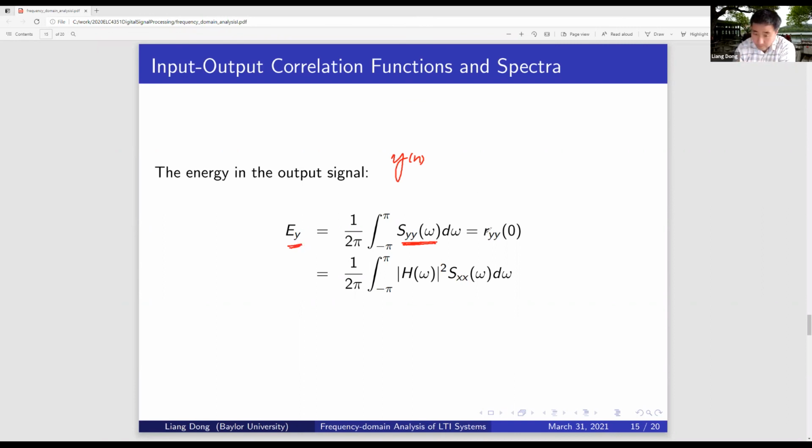And that is also equal to this autocorrelation of y and y when those signals align exactly on top of each other. So the lag is 0, which makes sense. So we got a signal y, let's say from here to here, and it takes the same signal y with the lag equal to 0, so you line them on each other, multiply each point, and add them together. Of course, you got the energy. That is when the lag is equal to 0.